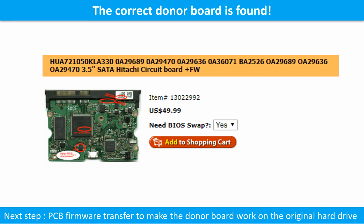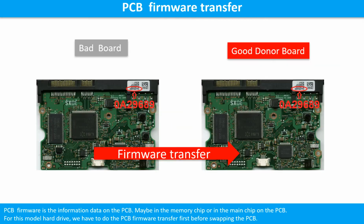We found the correct donor PCB board for the hard drive, but this is only the first step. The next step is we have to do the PCB board firmware transfer to make the donor board work on the original hard drive. PCB board firmware is the information data on the PCB board.